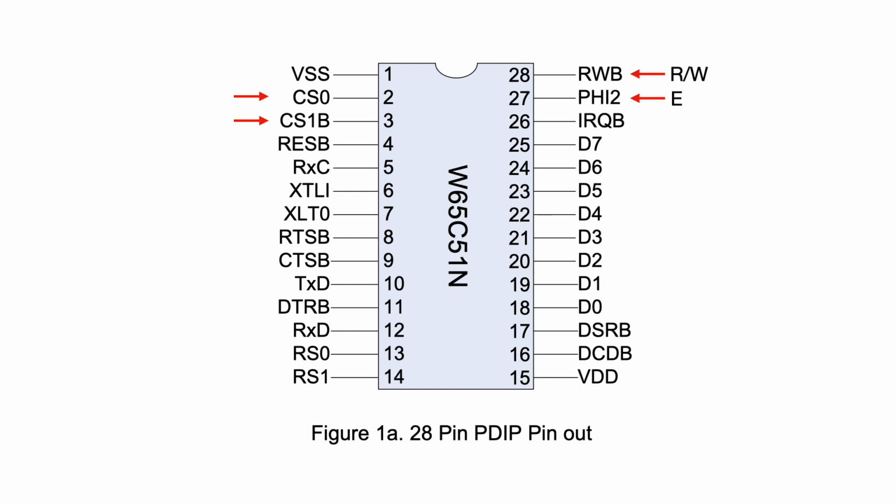This design pattern allows secondary address decoding to happen in parallel with the primary address decoding that asserts CS1 bar. If there were only a single active low chip select input on the ACIA, then the secondary decode to differentiate between the 2 individual chips would have to happen after the primary decode, which could cause those propagation delays to stack up. Anyway, that's just some additional context to keep in mind for a little later. The important takeaway here is that the peripherals with the synchronous bus interface, like this one, that are specifically designed to connect to 6502 or 6800, are trivial to deal with.